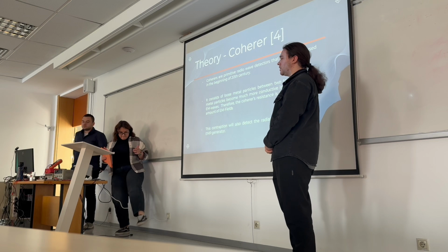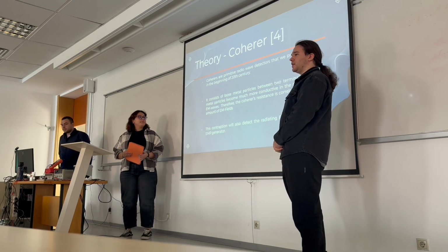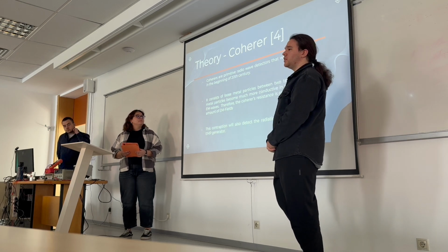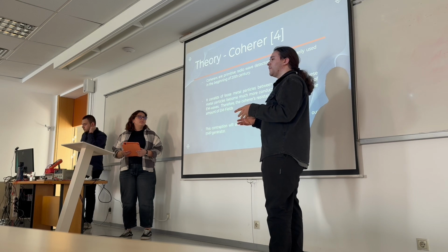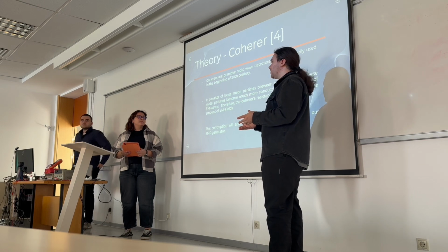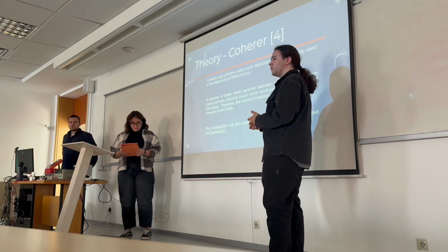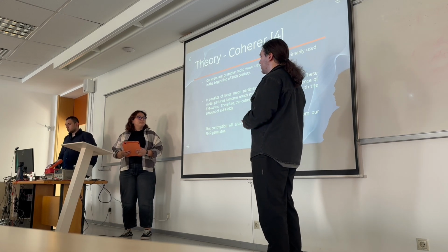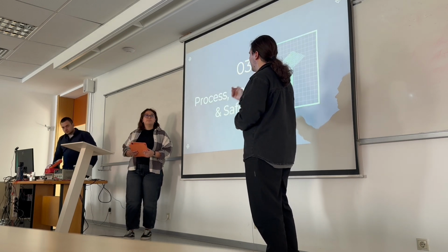Finally, we will test our circuit with a coherer. Coherers are primitive radio frequency detection tools that were used in the beginning of the 20th century. They house metal filings between two terminals, and once these metal filings detect electromagnetic waves, they become much more conductive, allowing for the measuring of the presence of EM fields. This contraption will be used to measure the EM fields from our EMP generator. And my friend Zeynep will take over.